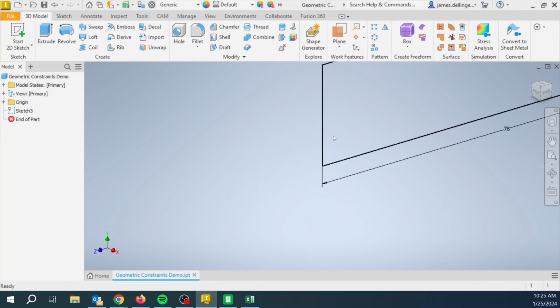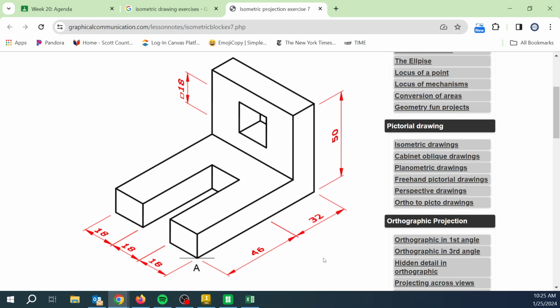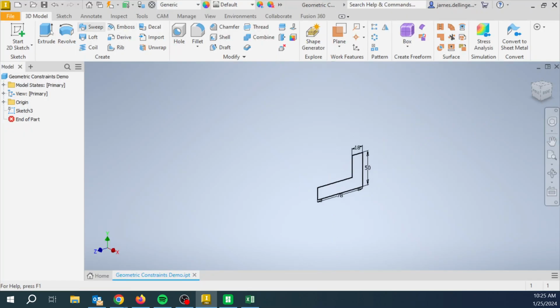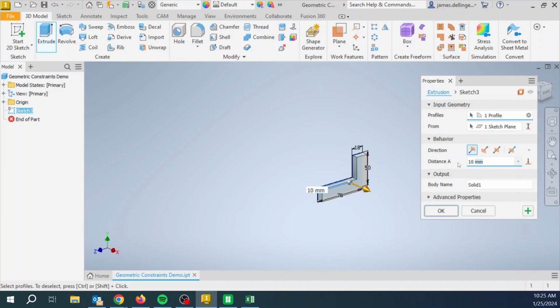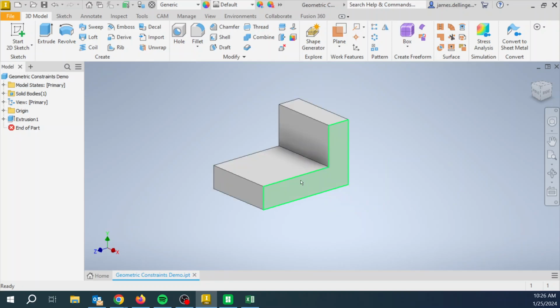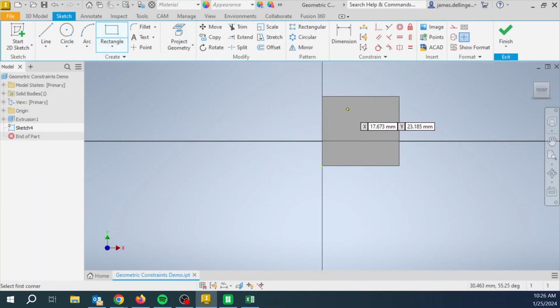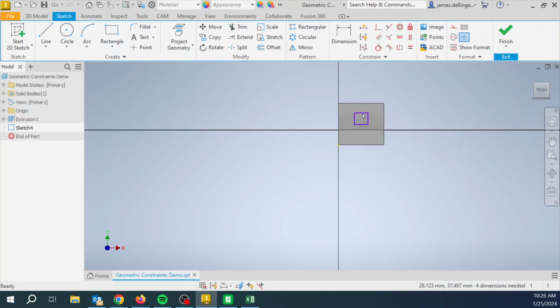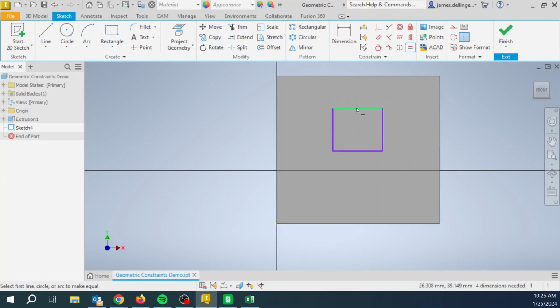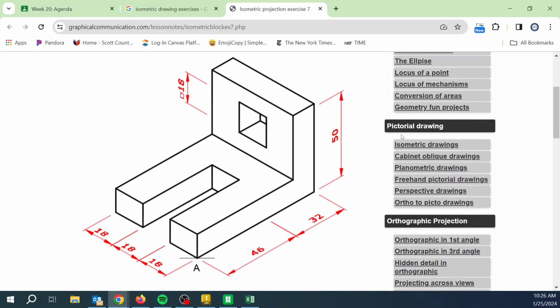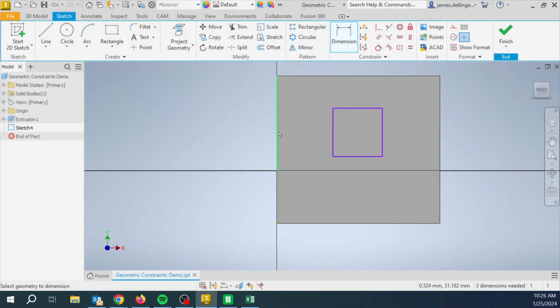And then we're going to finish, right? And then we're going to say, hey, this is whatever 18 times 3 is, right? And so we're going to say extrude, right? And then we're going to say 18 times 3. Right, make it do the math for you, and then we're going to go in and say, hey, on this face, make a sketch, throw your rectangle in, right, I'm going to say this is going to be equal to this because it's totally a square, that is 18, and I assume it's 18 and 18, all right, so that's going to be to there.